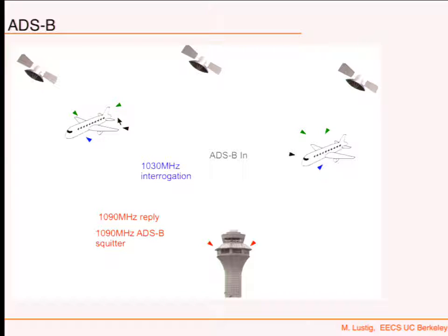And so now there are considerations of maybe encrypting it or putting some certificates on it and all sorts of stuff like that. But the frequency is 1090 megahertz, and the rate that the packets are sent is 1 megahertz, so 1 megabit per second. If you sample it at 2 megahertz, you're at Nyquist and able to resolve this in some way.